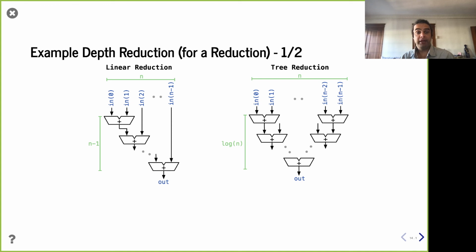And so yes, if there's a case where different inputs get different outputs, that's something the tools can't do, right? Like they can't change the design in a way that's going to cause you to see different outputs. That's something they don't want to do. Now, you as a designer might know that these numbers, despite being 8-bit signals, are never going to be that big. Or if it does overflow, you're okay with that. That's something that the tools don't know, right? This is kind of situations where you maybe do need to intervene.